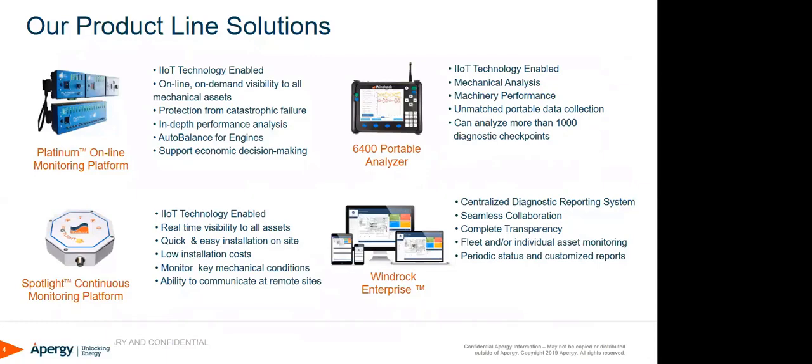In-depth performance analysis. It can be used with auto balance. We'll install automated fuel valves out on the engine, and it will adjust those fuel valves to keep the engine in equilibrium based on the peak firing pressure. And it can help support economic decision making.